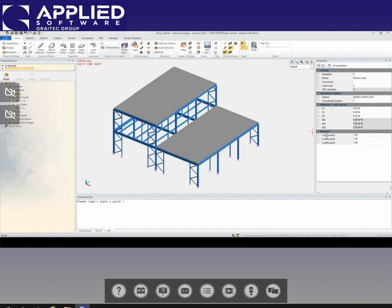I can put my intensity here. So for example, in Z direction, minus 20 pound per square feet. And I am in US or imperial units. But to change the units in Advanced Design, it's also very simple. You can just double click here and either change it to metric, or you can also have customized units based on your preference.